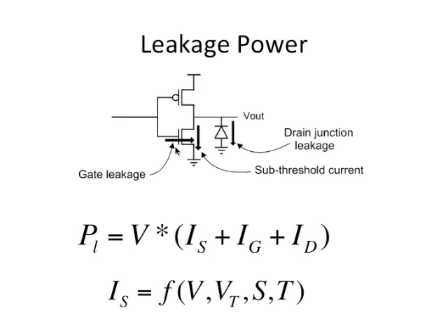Now in addition, I could also have leakage across the gate of the PMOS, even though the arrow is shown out here, but it depends on the logic state. Gate is supposed to be an ideal capacitor, but the gate oxide is very thin, so I will have some tunneling current through the gate oxide. So I will have some gate leakage, as well as the diodes out here, they will also leak.